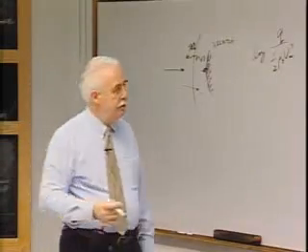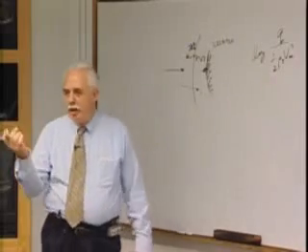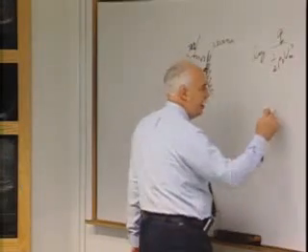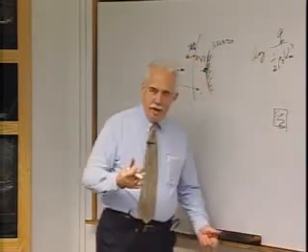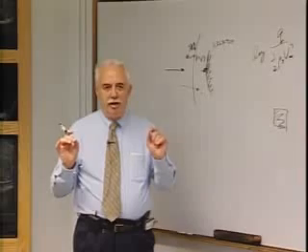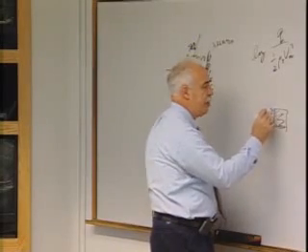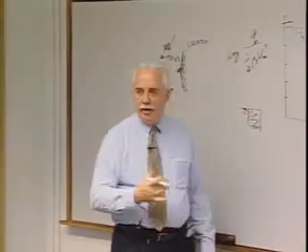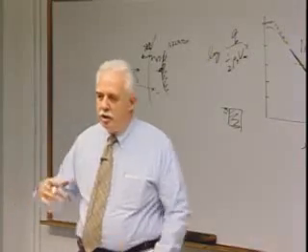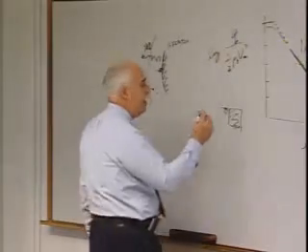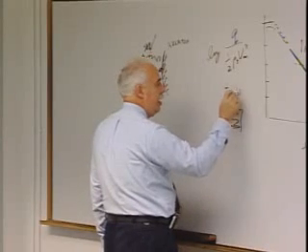Now in the ablator, that char, think of it as a charcoal briquette, okay? You start with some material, it degrades and all sorts of chemical reactions go. If you've got a good ablator for our application, what happens is you're left with a residual char, which is black and very high emissivity. It's pure carbon if you want, okay? That's the challenge, is to get a carbon surface or a high emissivity, high temperature surface that can re-radiate.